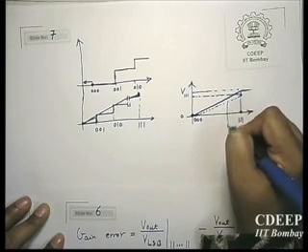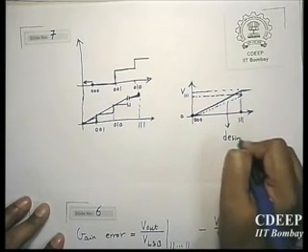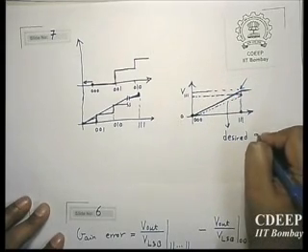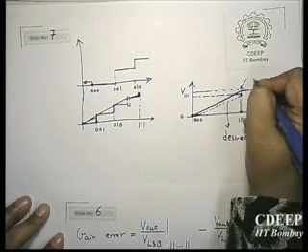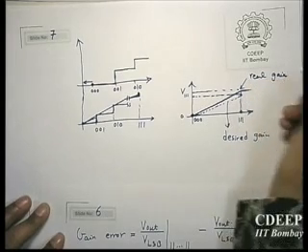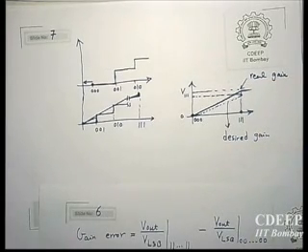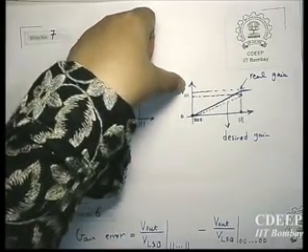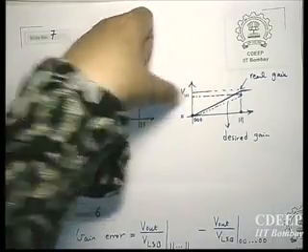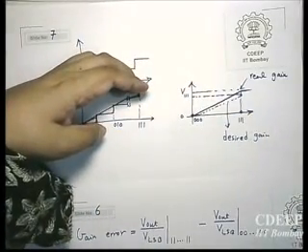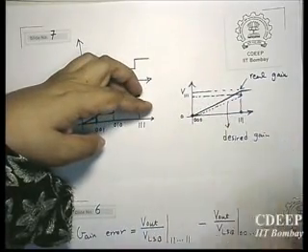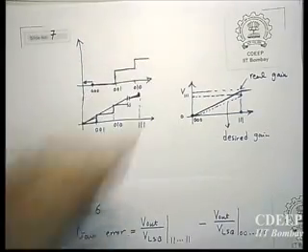So this was desired, and this is in fact desired gain, slope of this line, and this is real gain. So what we are doing is that we are making the code corresponding to this, which is eventually 2 to the power n minus 1 multiplied by LSB size, minus 0, minus 2 to the power n minus 1 LSB size.